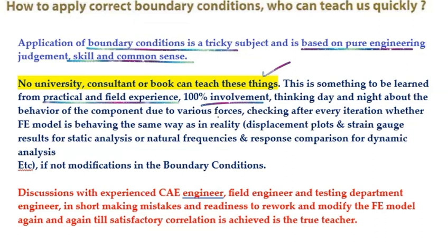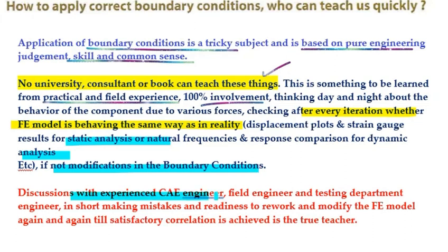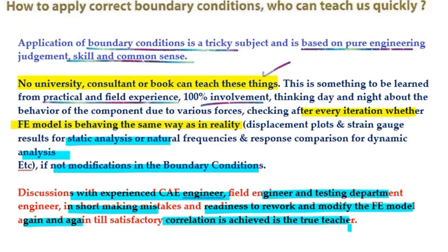of the component due to various forces, checking after every iteration whether the FE model is behaving the same way as in reality. Displacement plots and strain gauge results for static analysis, and natural frequency response comparison for dynamic analysis, have to be compared. If not, we need to modify the boundary conditions. Discussions with the CAE engineer, field engineer, and testing department engineer are needed. In short, making mistakes and readiness to rework and modify the FE model again and again till satisfactory correlation is achieved is the feature.